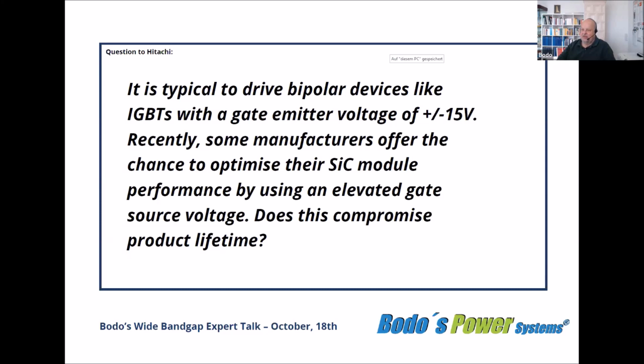That's what the IGBT is. It has a MOS input side, so it's not like a bipolar with a current magnification. Recently, some manufacturers offer the chance to optimize their SiC module performance by using an elevated gate-source voltage. Does this compromise product lifetime?